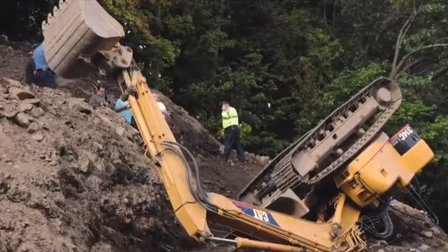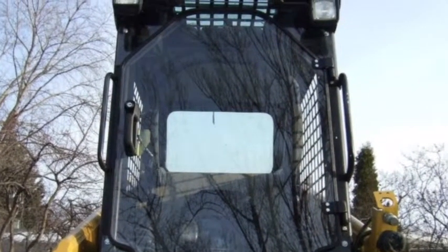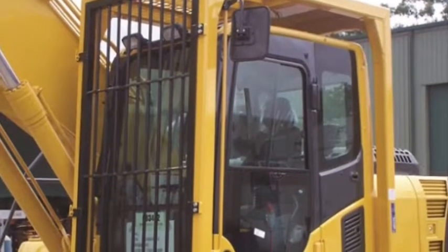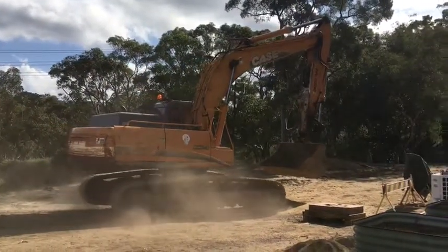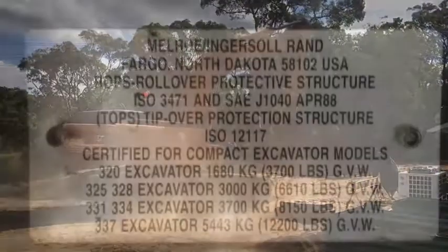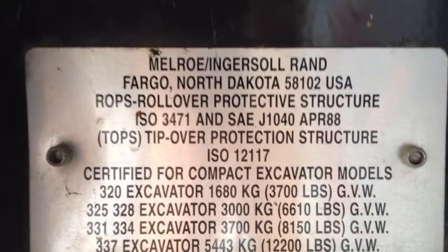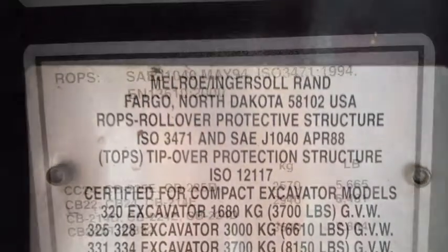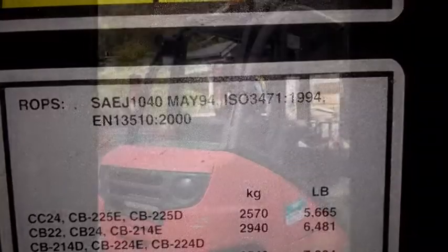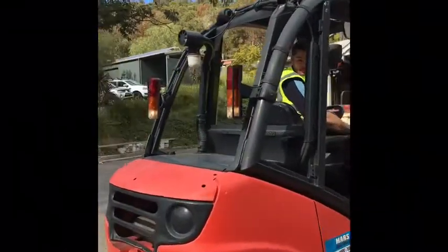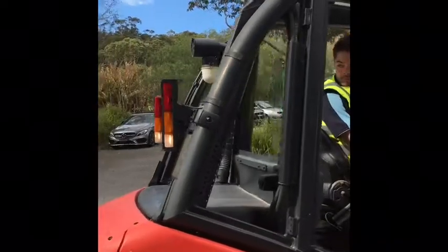Items to look out for while inspecting these include corrosion from age or exposure to moisture, modification to the structure, and excessive vibration, for example in rollers, which includes metal fatigue, and incorrect reinstallation from old pieces of plant to new ones. When a piece of plant includes ROPS and/or FOPS, a compliance plate will be fitted to the frame which states the relevant standards that the piece of plant was originally manufactured to comply with. Make sure the piece of plant has a working flashing beacon and an audible movement alarm fitted.